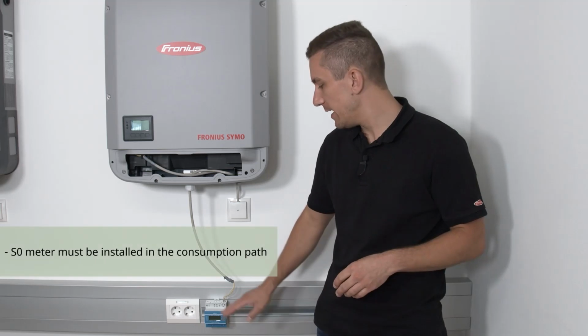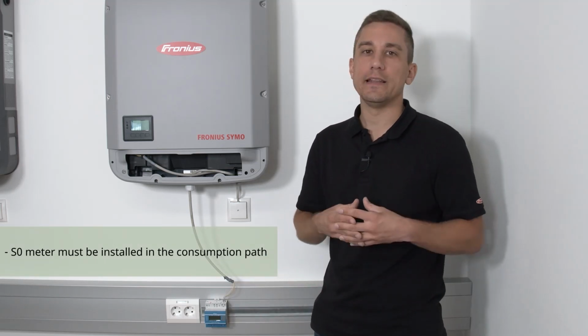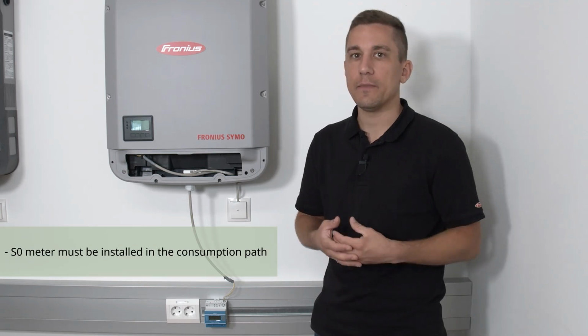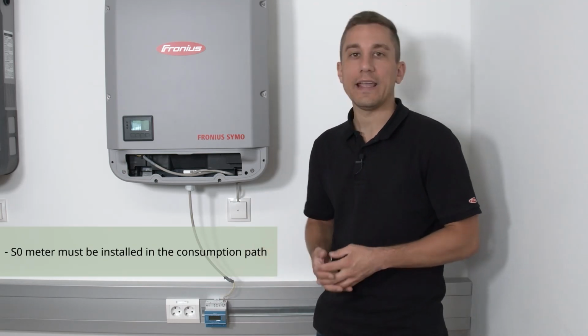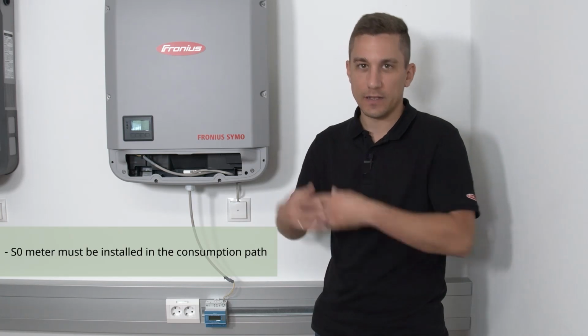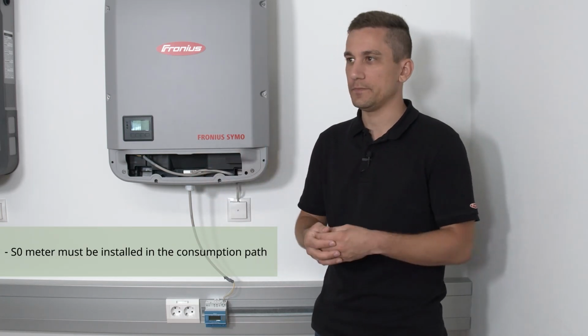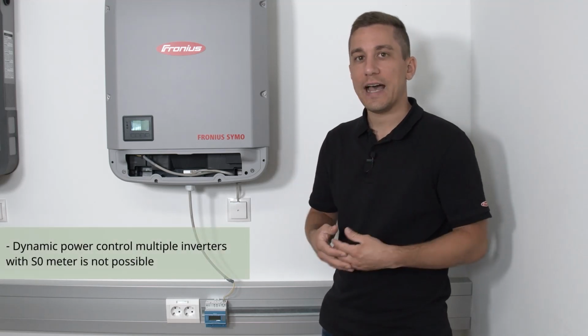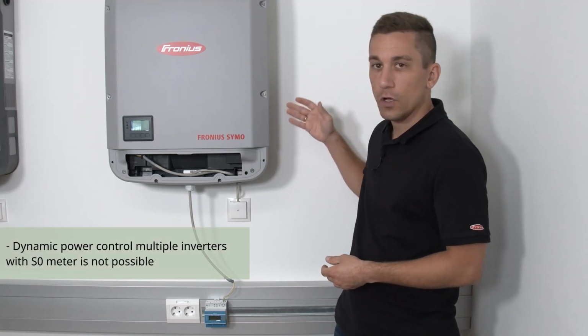Please note also the S0 meter must be in the consumption path, in the load path of the system. This is very important so that we get all the energy flows within the system between the PV system and the local grid.